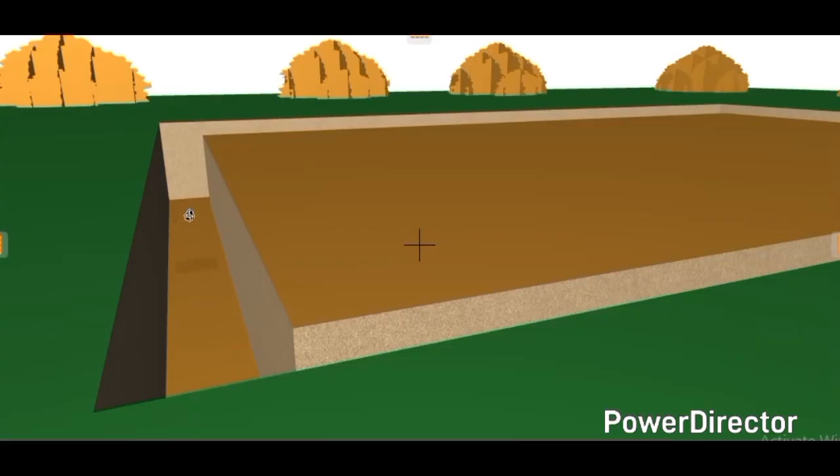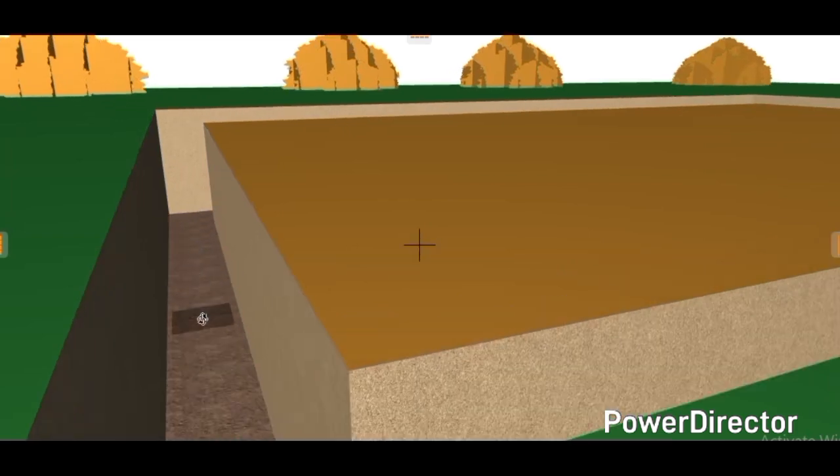When compacting this, now let us compact this. We're going to adjust some of this soil here and then we do the compaction. Now you see we have done the surface treatment. Now let me take you close range. You see this is soil that we have just returned, very close range, and we have compacted it, and it is now straight to receive the blinding.